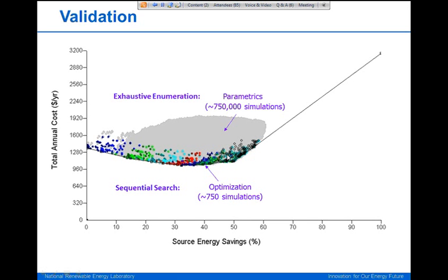And so depending on what simulation engine you're using, if you're running optimizations, as I mentioned, you might be doing 1,500 or 2,000 building design evaluations in an optimization, depending on how many options you selected on the input screen. But this is a matter of some hours of computational time. You may want to do optimizations overnight, but at least you don't have to have 50 computers running for 3 or 4 days to get this result for a given building analysis in a particular climate.